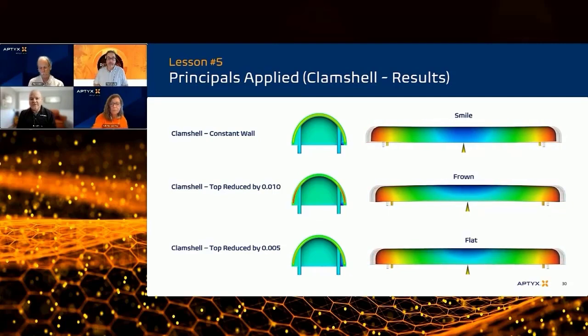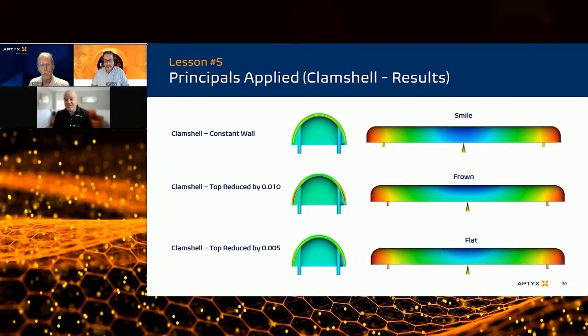Yeah, that was the final point for me. You get to the point where you're sacrificing mold maintenance costs, things like flash and wear, because of the differential temperatures on the tool. My experience has been that sometimes you get lucky and it can help, but the root cause is generally the material, the geometry, and where you place the gates. If you can improve that on the upfront side, you won't have to be tweaking the process to an extreme. You'll have more process window and flexibility, which makes things more cost effective.